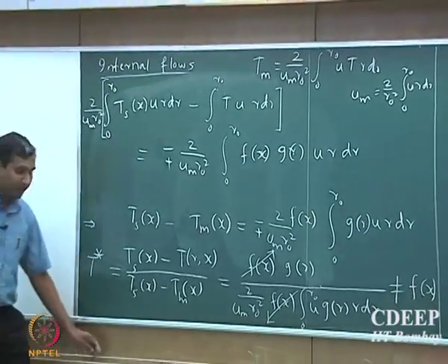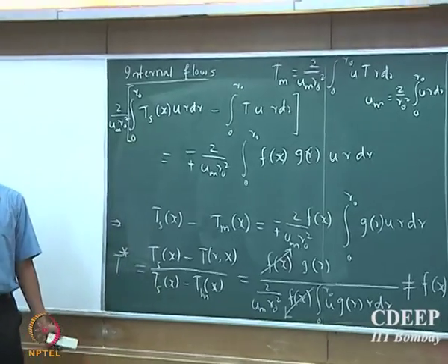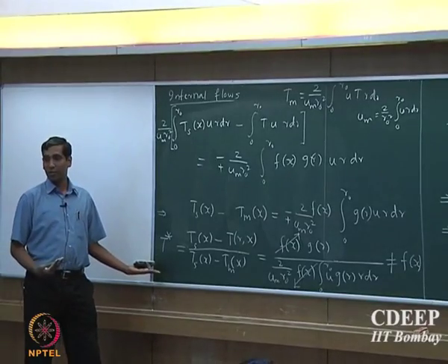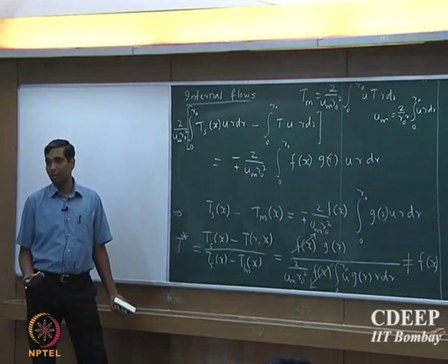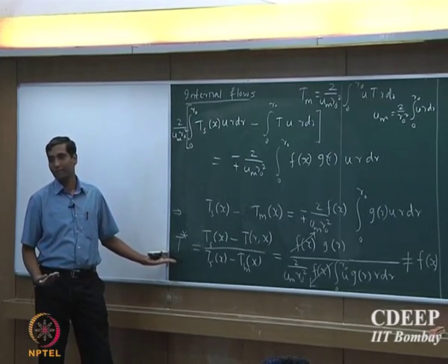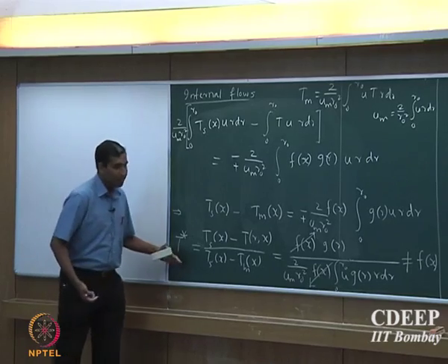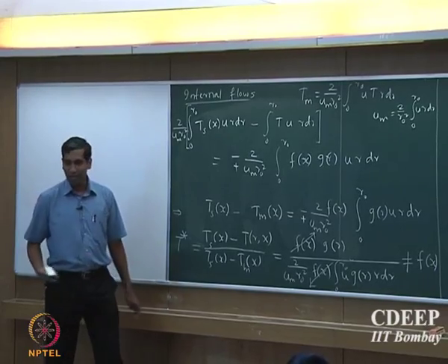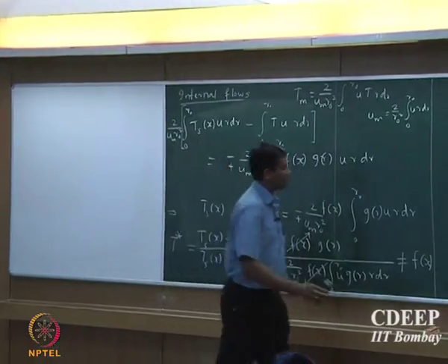Okay, so this is a fundamental difference between the momentum boundary layer and the thermal boundary layer in internal flow case. So it's not the temperature profile which is not changing, it's the dimensionless temperature profile, it doesn't change with the axial position. So this observation actually can lead to some really interesting and intuitive results, which is what we will see in a short while.